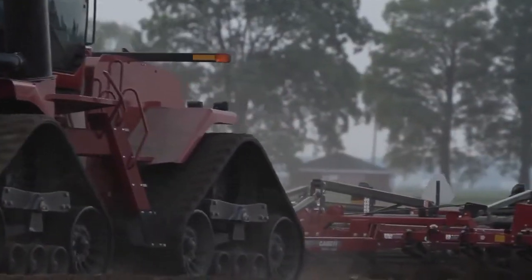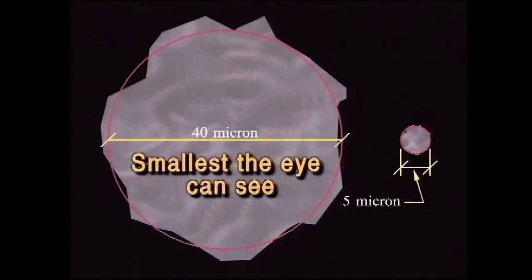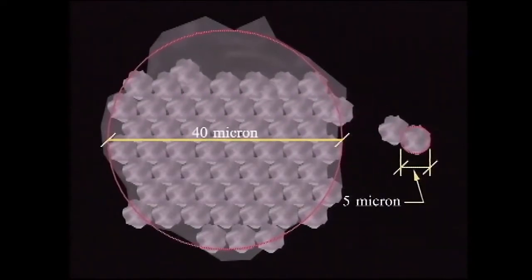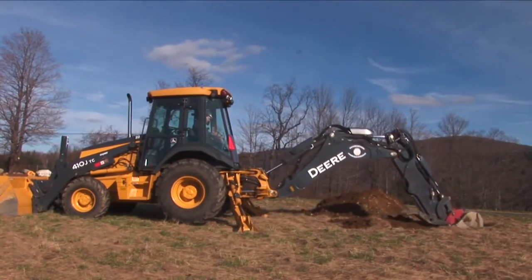In order to visualize what a 5-micron particle looks like, let's start with the smallest particle that we can see, the speck of dust you see on your TV screen, which is 40 microns in diameter. You might conclude after a quick glance at the numbers that a 5-micron particle is 1/8 the size of a 40-micron speck. But to properly compare size, you must relate the cross-sections of the particles, not the diameters. As you can see in this representation, the 5-micron particle is actually 1/64th the size of a speck you see on a TV. Due to the tight clearances in today's systems, that small a particle can be the beginning of premature wear and efficiency loss.